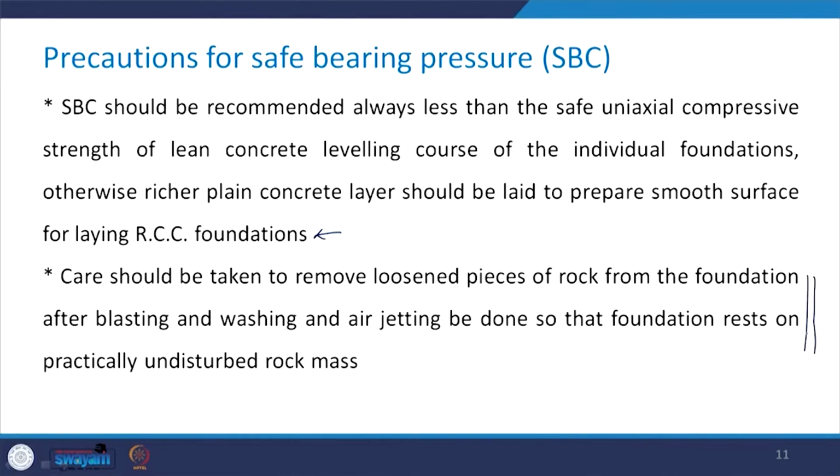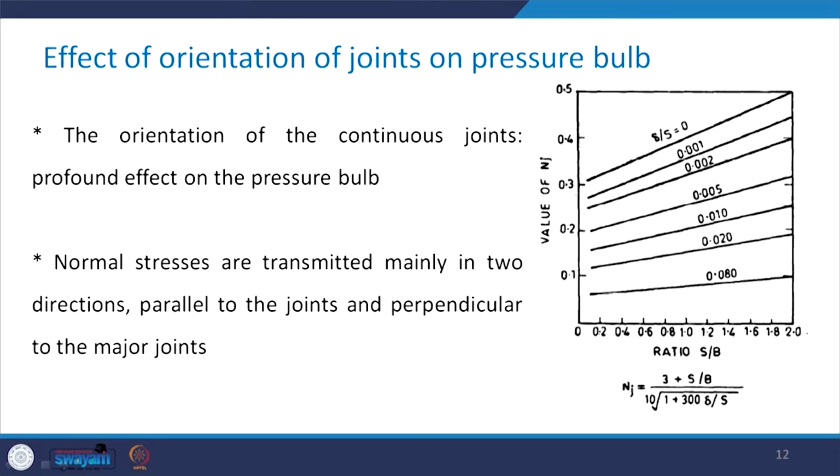If this is not done, then whatever bearing capacity the foundation would have had if it was placed on the undisturbed rock mass will not be achieved, if you are not carrying out this particular step, that is washing and air jetting. So, one needs to be extremely careful.